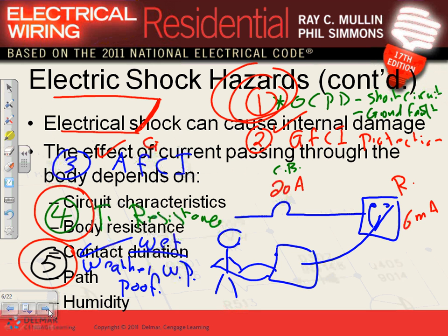The text states that it will only operate properly on a grounded system. If they have knob and tube, are you out of the picture? Which one are we talking about now? GFCI, the ground fault protection. The diagram doesn't indicate anything. Yeah, the ground fault protection we really can install in an ungrounded system like knob and tube.